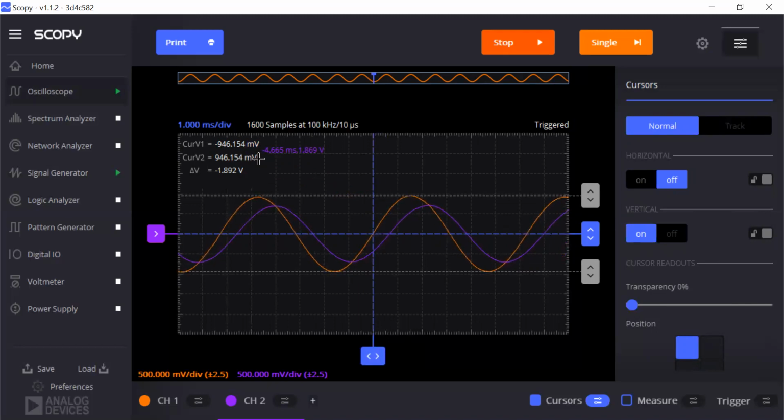The amplitude of a signal is 1/2 that, so that should be twice the amplitude. And you do want to measure from peak to peak as opposed to just offset from the origin, because there are some DC noise offsets here.